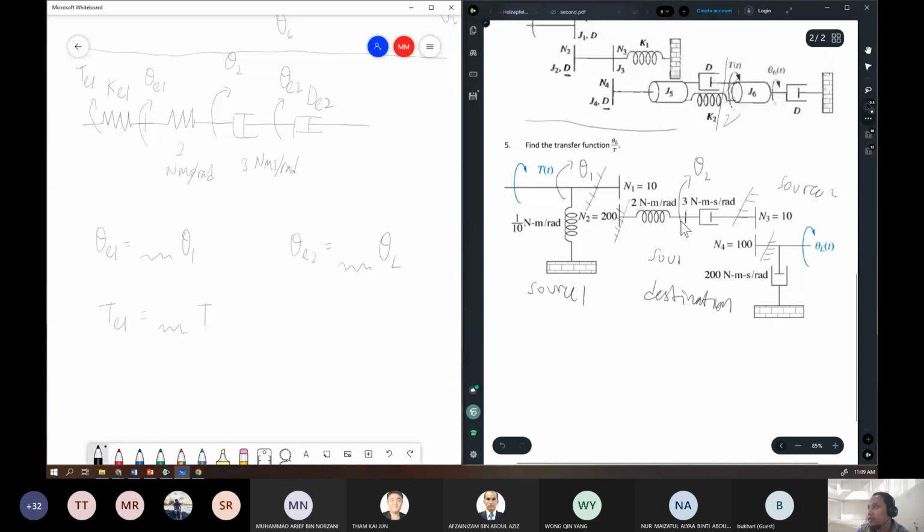The location of theta I put in between the spring and damper, because as I said earlier, if you have 2 things connected in series, the point in between them has a degree of freedom. Theta 1 measures the rotation for the first section. Even though it is not shown in the question, from our deduction just now, when you fix the things, there is actually a theta here, a degree of freedom. So you just put theta 1. Okay, thank you, Doktor.